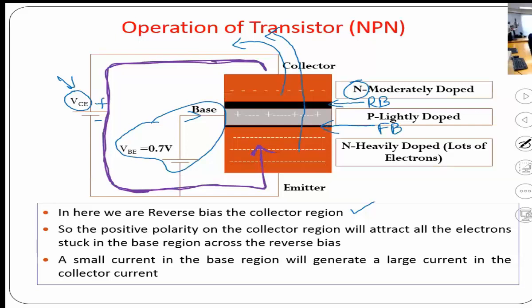The advantage of a transistor is all you need is a very small current on the base, but you can control the current on the collector side. And the load will be placed somewhere here. Load in the circuit on the transistor is always from the collector perspective. For example, you can have a motor, a lamp, or whatever that device is.